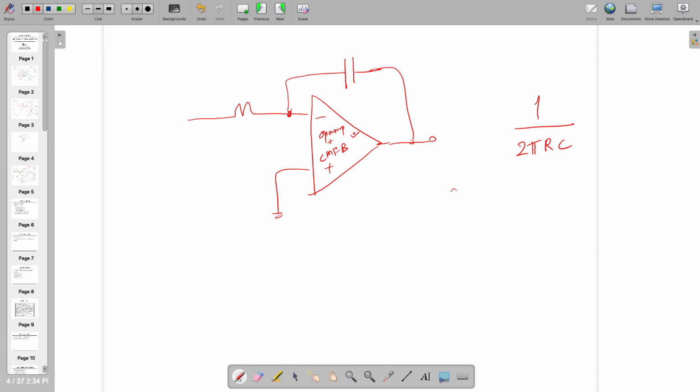Maybe at one corner you are seeing 1 kilo, at another corner you are seeing 1 mega. So resistance is either decreasing or increasing, or capacitance is increasing or decreasing, because there are two more corners. One is called R typ, one is R min, one is R max corner. Similarly, C typ, C min corner, and C max corner. So on top of 125 corners, the corners will be increasing. So these values are also increasing or decreasing with the value of capacitances, value of temperature. These things will be changing.